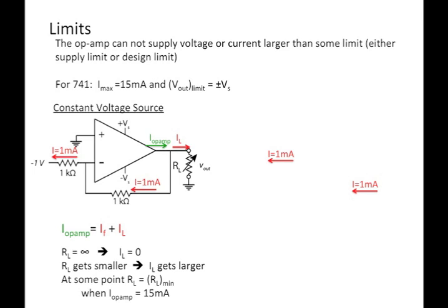All right, I guess we're on to the next slide. So those are the basic circuits that we talk about: amplifiers, differential amplifiers, summers. Those are some of the basic uses for op amps. But it turns out when you actually go to use those op amps, there's certain limits, right? If you put in a 10-volt signal and your gain's 100, well, you may not be able to output 1,000 volts. And so there's some limits on what determines those limits.